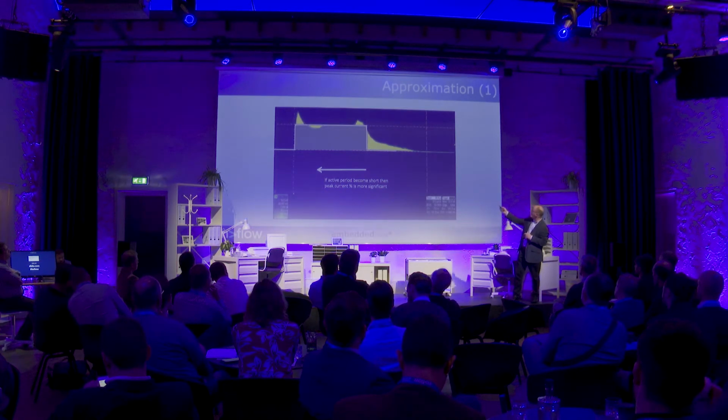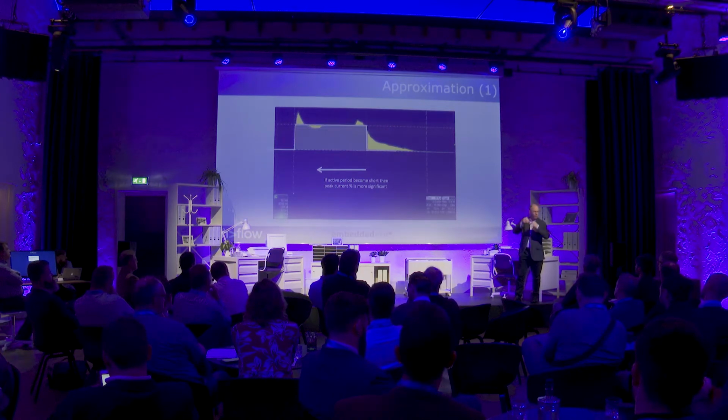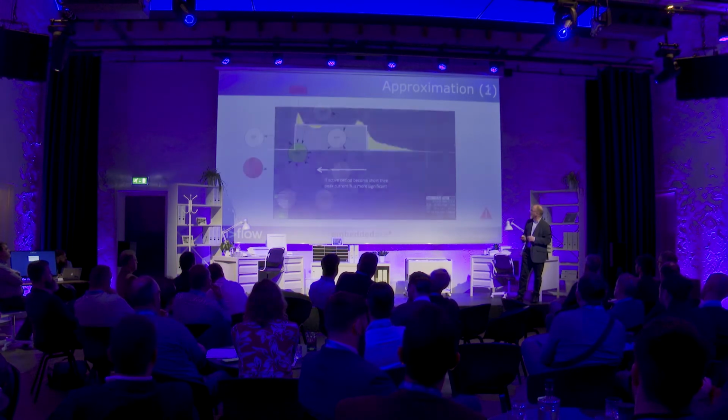And look at that long tail. Okay, if we're waking the microcontroller up, powering it down, waking it up, powering it down on quite a fast cycle, it may be that with that long tail, we're actually stepping into it, and we wake the microcontroller up before it's really got into the low power mode. That's going to have an effect on the battery life as well.